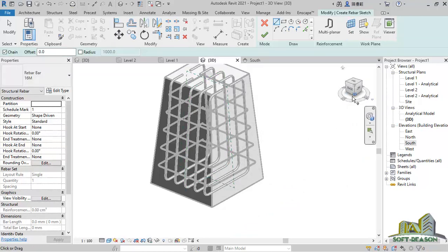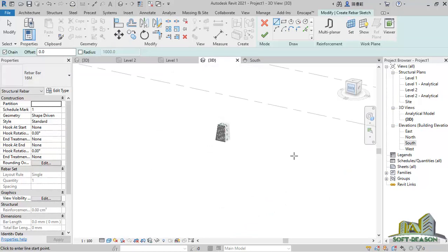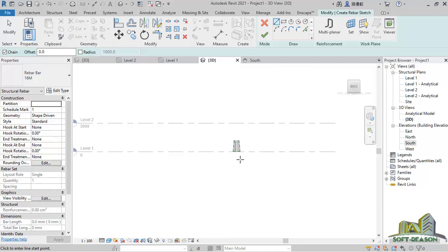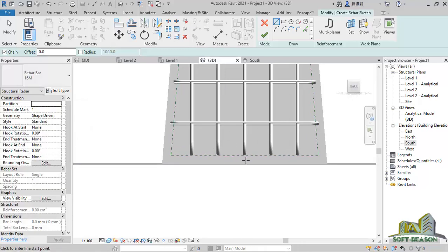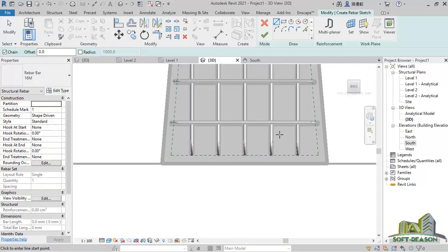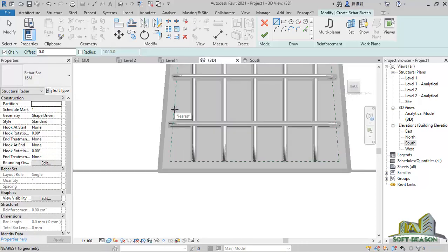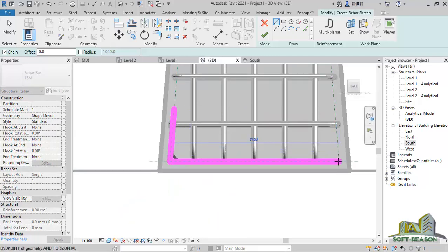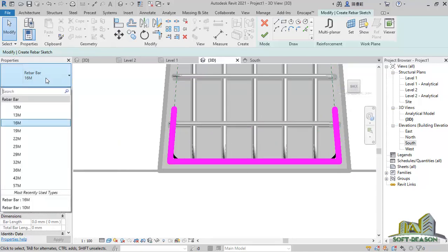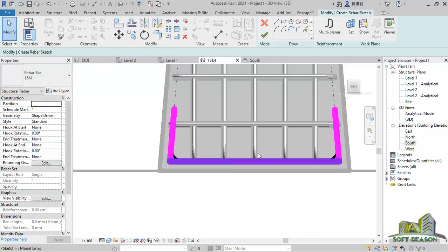Okay, facing the back. So we just activate the back now. Click on that. So once you activate the back, zoom it closely, and then you start sketching your rebar. Okay, so we want to start sketching the rebar all the way from this point. Pick that point, pick this point, pick here and extend it also up to this point. Click that. Okay, deselect that, change this diameter. Okay, we will still be using a 16 in these provisions. Okay, so click on finish.